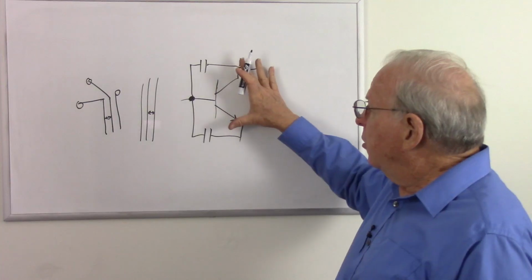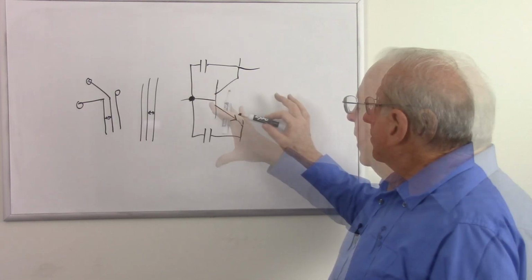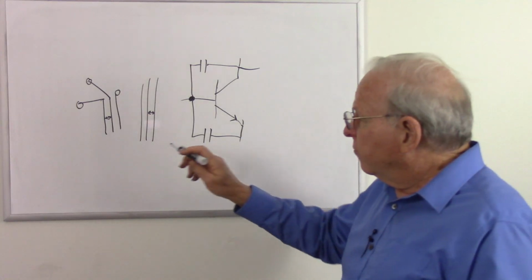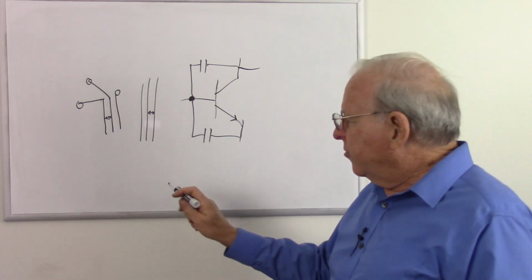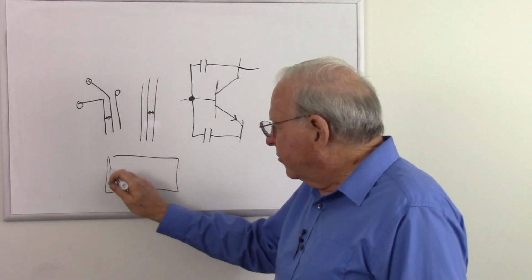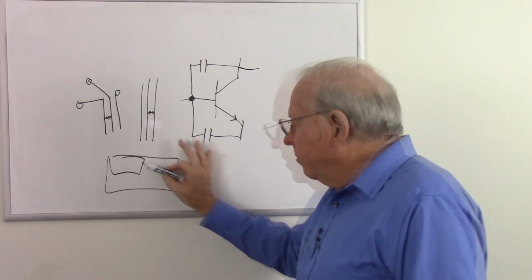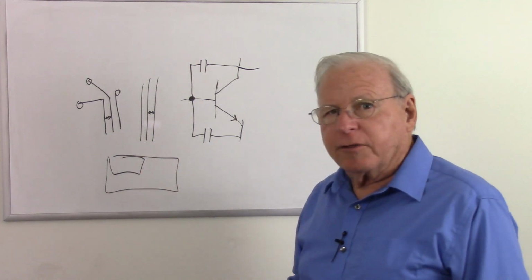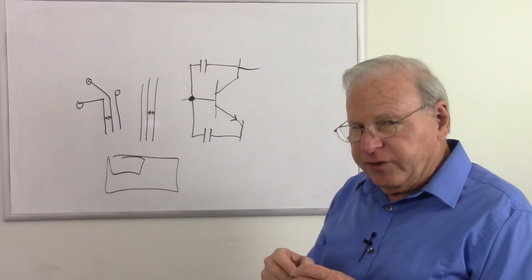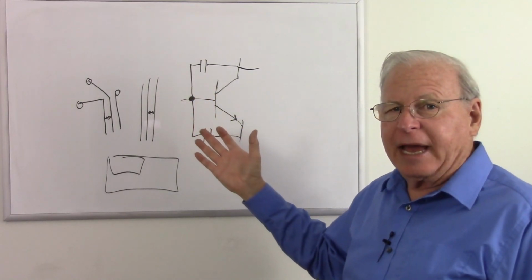We have special components that have less capacitance so they can work at higher frequencies. And we have to design our circuit boards to avoid these parallel traces. And sometimes you'll see circuit boards have little metal boxes here and there. That is to block some of the radio frequencies from getting from one part of the board to the other. So as frequency gets higher and higher, we have more and more trouble mitigating the stray capacitance.